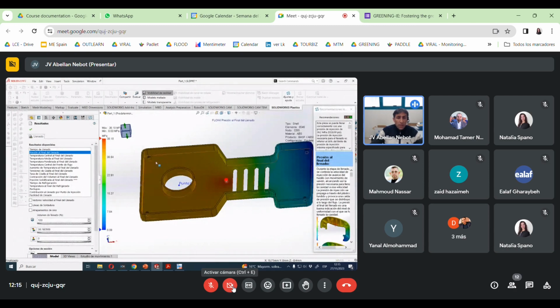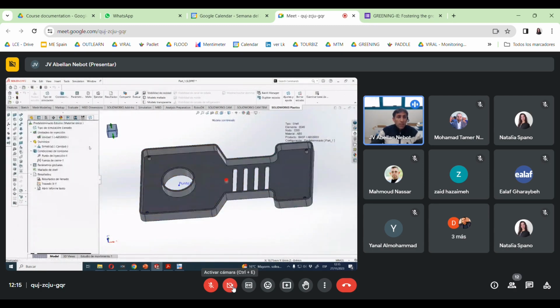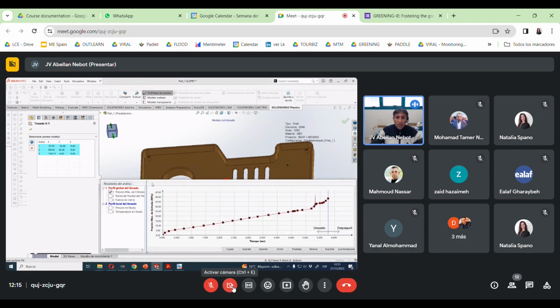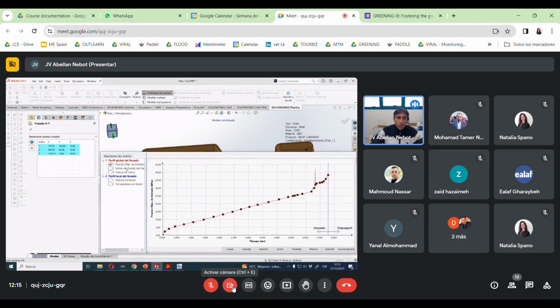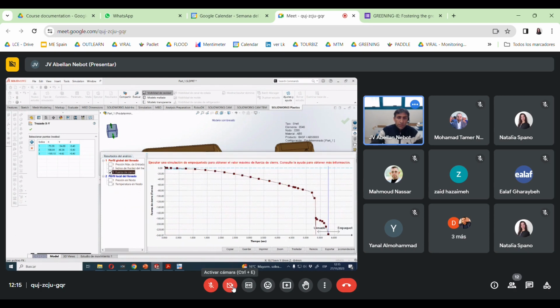And now let's see about the clamping. What happened with the clamping force? If we go to the XY plot, we can see the clamping, exactly the same as before. We need to click clamping force. Here the clamping force reaches, there is something here that changed a little bit. We should see what happens here, but anyway, let's assume that this is around 240. Maybe this is because of the settings that we didn't change, but it's 240.